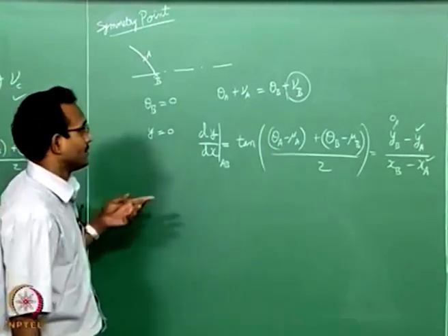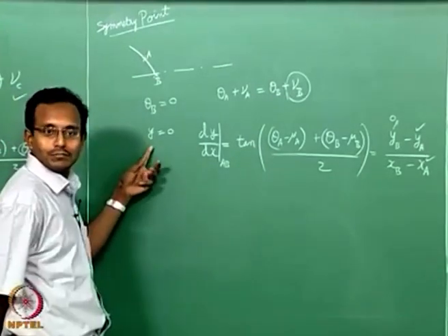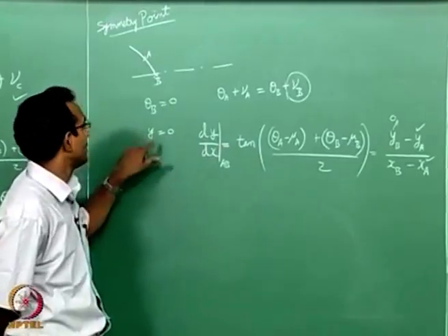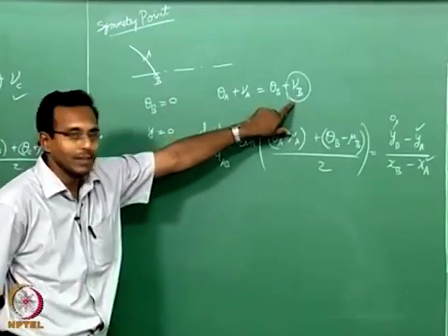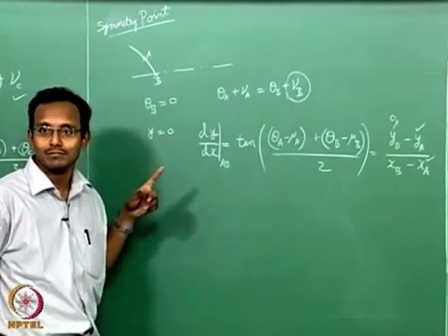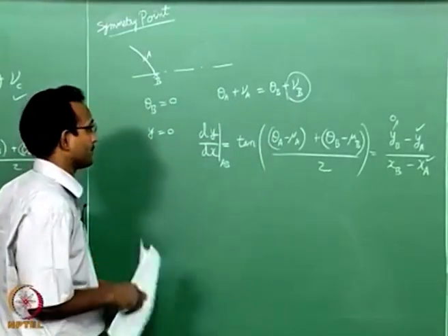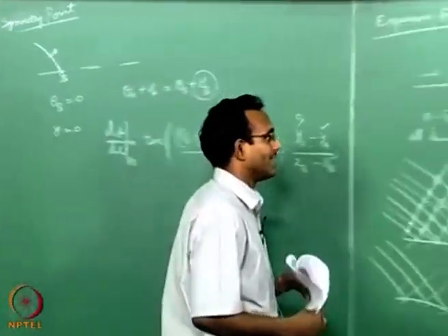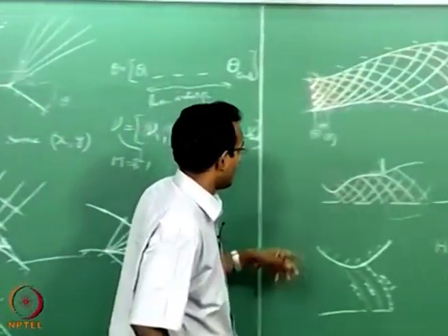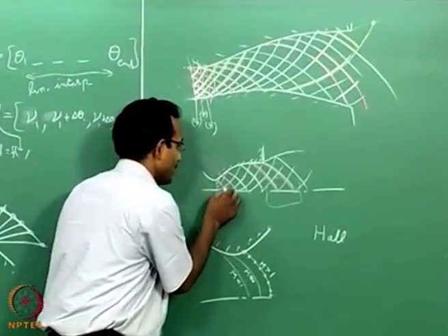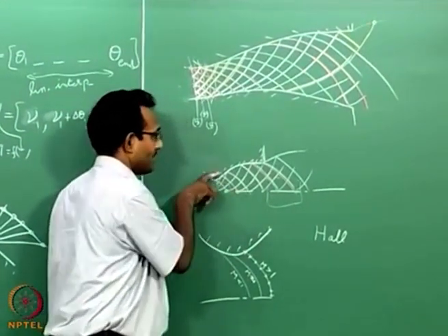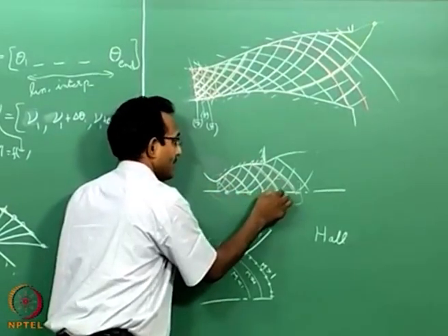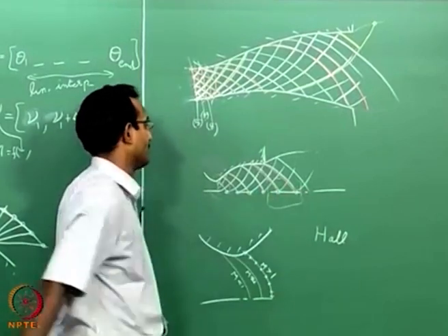Okay. So, y b is 0, x b is known, x and y are calculated, theta b is 0, nu b can be calculated. So, I know the full point. This is the way it is solved from there. I skipped this, I should have included that, and that is the subroutine you will have to use at these symmetry points. Every time this negative characteristic comes and hits the axis, you would use this symmetry point routine for all those points.